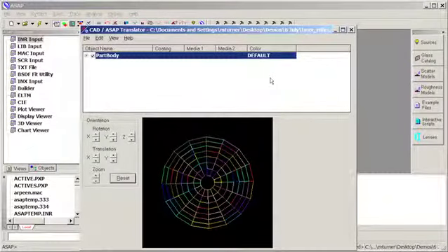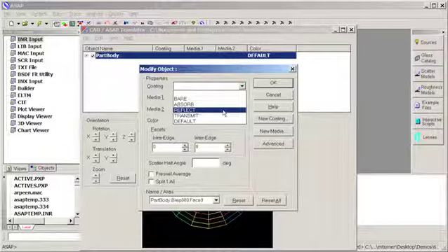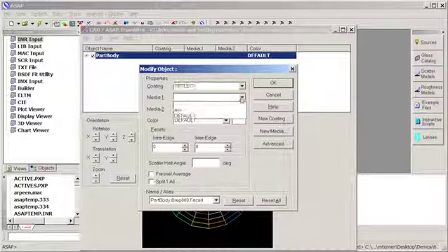And here's the part that's been imported into ASAP, and I can come into this importing option here, and I can define some new parameters. Since I know this is a reflecting surface, I can assign a reflecting coating to the object as a whole. I could also do this within my ASAP script as well, but I might as well do it in this location.